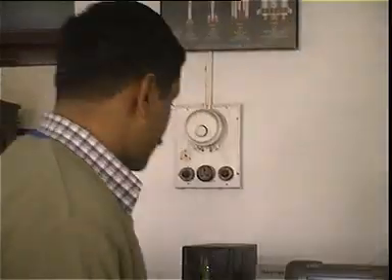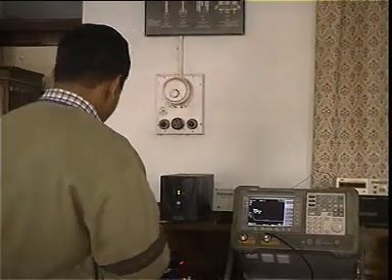So it is obvious that the power spectrum should appear as sinc square spectrum. But where should the center of the sinc square spectrum be? It should be around the carrier frequency. So I'll expect a sinc square spectrum to be located around 2 MHz, because 2 MHz is the carrier frequency. Let us see that on the oscilloscope, on the spectrum analyzer.